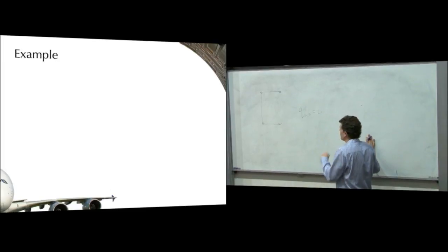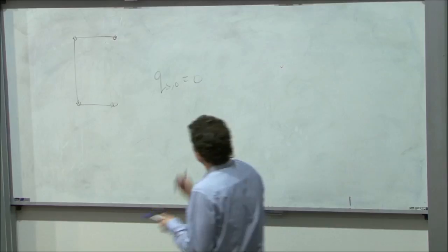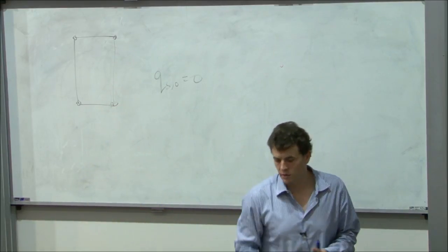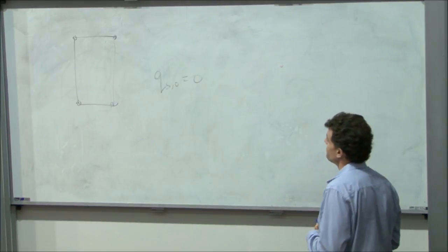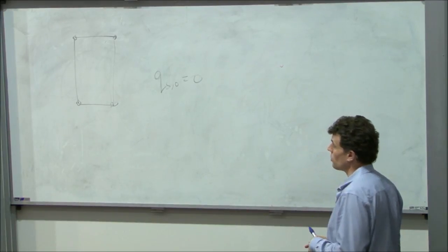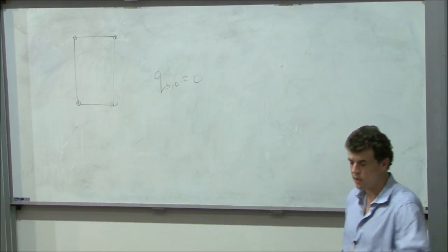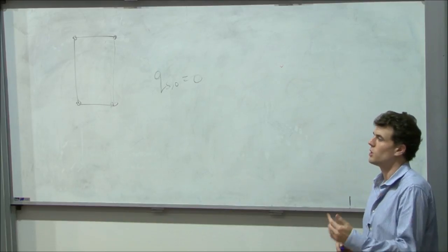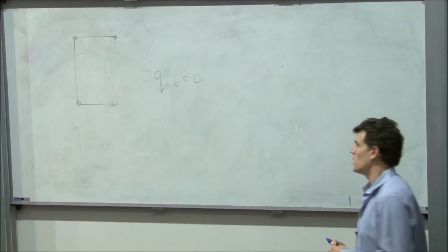Okay, we relied on that, but if this was a closed problem, we can't do that. There's nowhere to start. So what do we do to solve that? Well, we do exactly the same as what we did last week, and we use a moment equilibrium to work out what our unknown shear flow is.